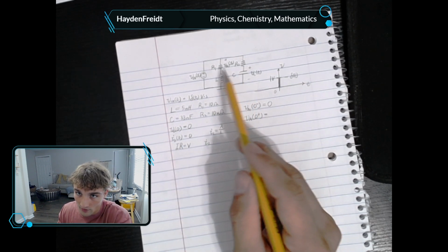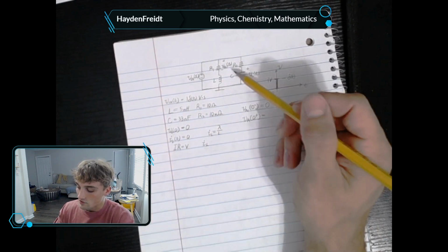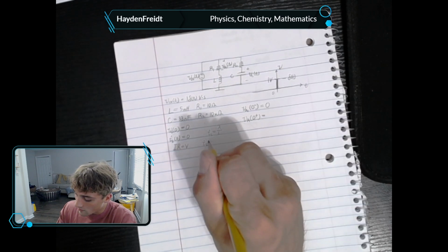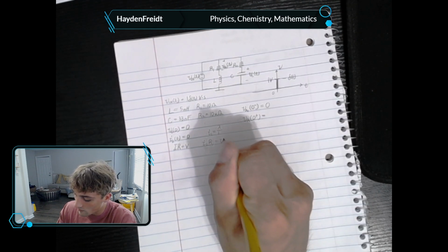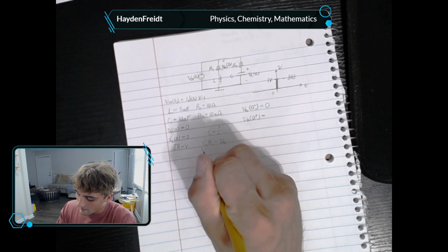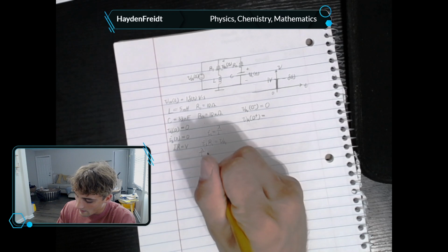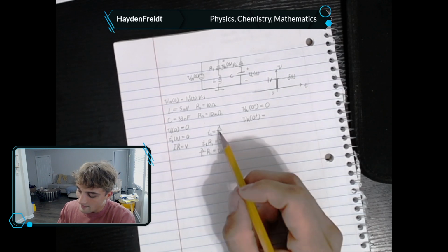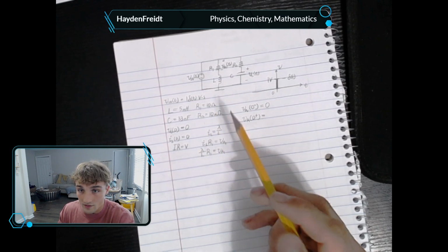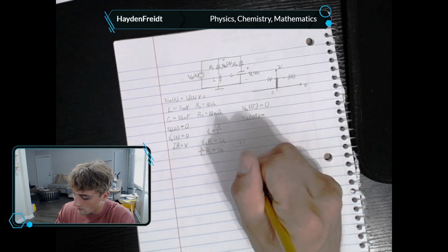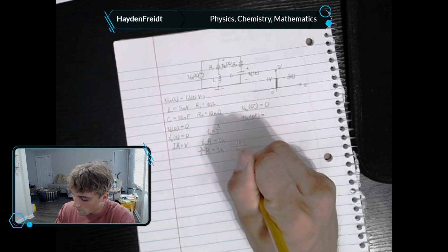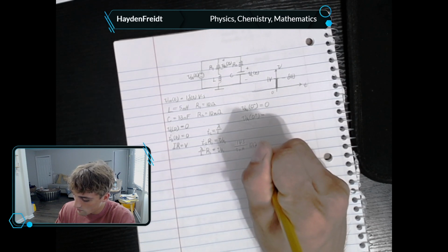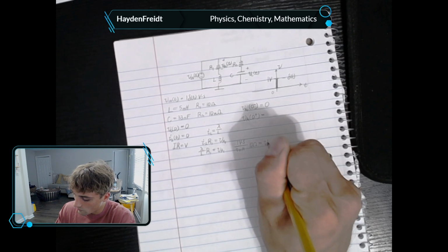Okay, those two branches are decoupled. So now, considering that these are decoupled, we're going to have the same amount of current flowing through both of these components. Okay, so IL times R1 is going to give us VR1. And we just plug in this magnetic flux divided by L multiplied by R1 equals VR1. The magnetic flux, because we have a voltage impulse, is directly proportional to the voltage impulse. 1 volt second divided by 5 millihenry multiplied by 10 ohms is going to equal VR1.